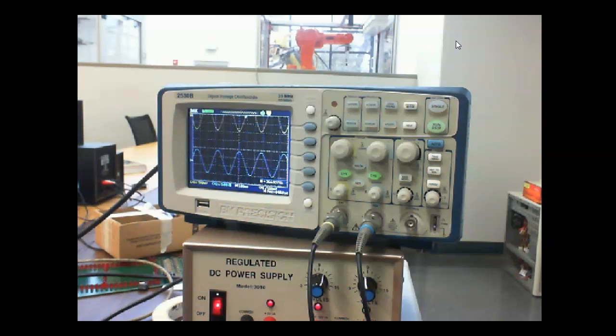That's why you have the polarity on the speakers. It tells you to take the same wire that you hook up on one and hook it to the other. You're putting AC on those speakers, so you can't hook up those wires any way you want to. If you hook one up backwards, then when this one's going out, the other one's going in, and you're not getting the sound you want.